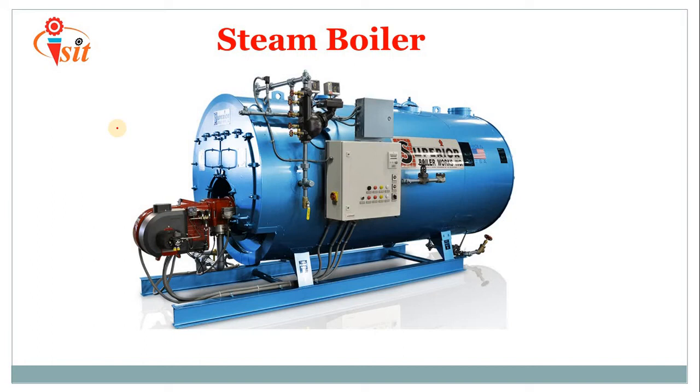And when we talk about accessories, there are a lot of them. Again, the air preheater is there. The air preheater is most important to heat up the air for proper combustion, as we need heated air. It also plays an important role in absorbing the moisture from the gas as well as from the pulverized coal.